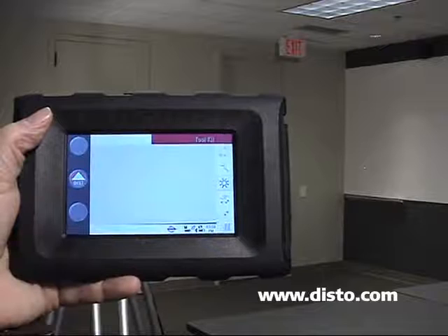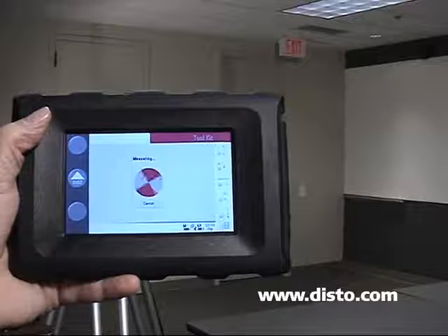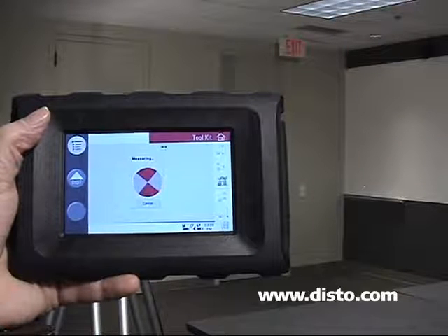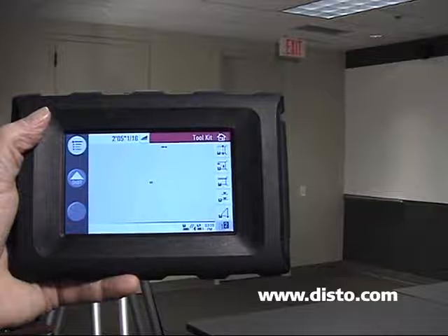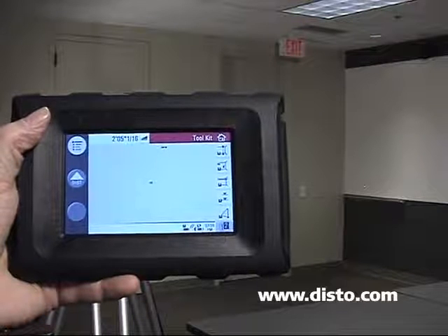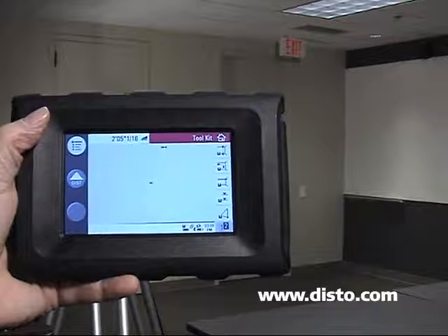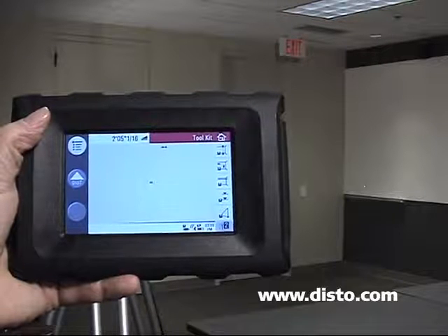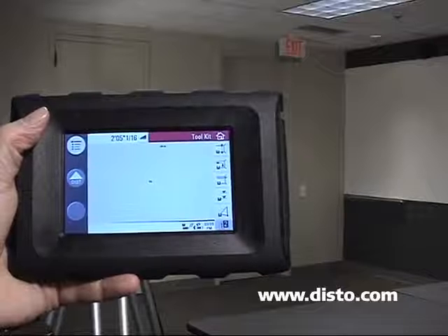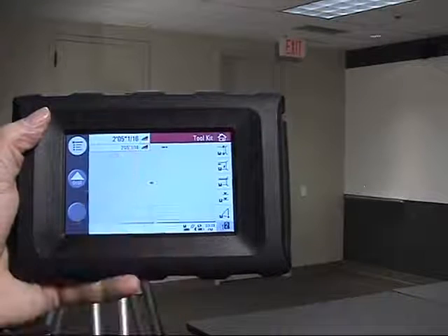We're going to go ahead and hit the Dist button. Now the 3D Disto is calculating and measuring. It has come down and put a new flashing red light on the exact same height or elevation as our reference height when we first started measuring. You'll see the distance that we've also traveled is 2 feet 5 inches, as shown in the result screen.